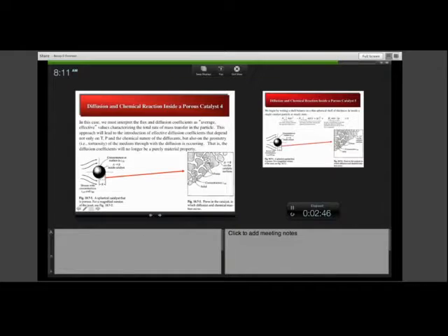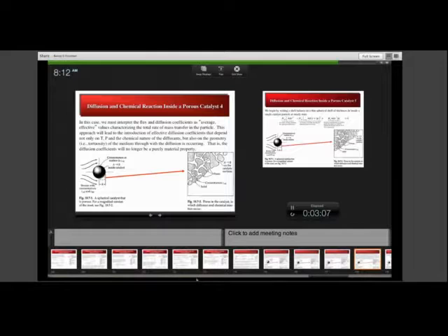And so for purposes of mass transfer, we will treat this catalyst particle as being a homogeneous mixture of gas and catalyst. And the way we will do that is that we will define concentrations, for example, of gas A and gas B at a point. So we'll develop expressions for concentration profiles of A and B that vary with radial position.